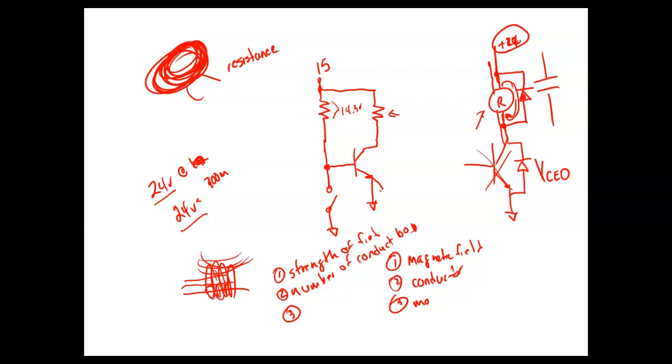And we'll show y'all this. So what I'll do is I'll use a coil, and I'll charge the coil up to about 12 volts. First of all, we'll look at the neon bulb, and we'll see that the neon bulb takes about 90 volts to turn it on. And then I'll hook it across this inductor, and then I'll charge it up to 12 volts. And when I turn it off, you'll see that neon bulb comes on, which means that thing had to discharge at least 90 volts to turn that bulb on. So we'll show y'all that next class.